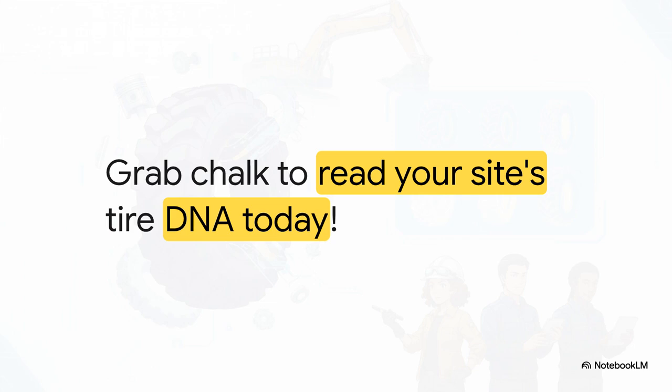The next step? Well, that is entirely on you. The absolute best way to lock all of this in is through real-world visual engagement. I mean it. Grab a piece of chalk and physically circle those L5 or E4 codes. Grab a tread gauge to physically measure the difference between a standard L3 and a massive extra deep L5. Go read your site's tire DNA today. Bringing this knowledge out of the classroom and actually checking your fleet is exactly how you prevent those $1,000 mistakes and, more importantly, keep your operators safe.